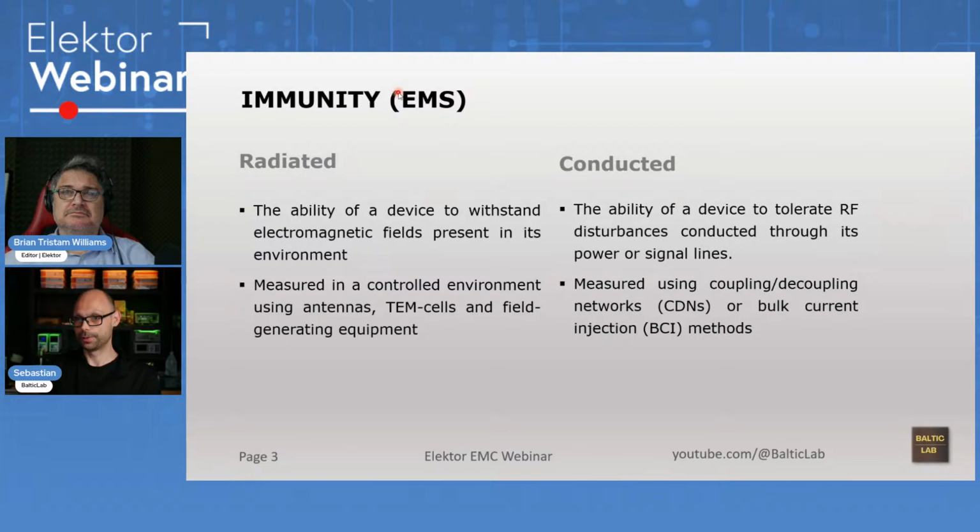Then, of course, the reverse for the electromagnetic interference over wires would be the susceptibility through wires. There can be noise on your power supply lines that, of course, spreads to other systems. And if those systems aren't immune enough, this will, of course, also cause issues.